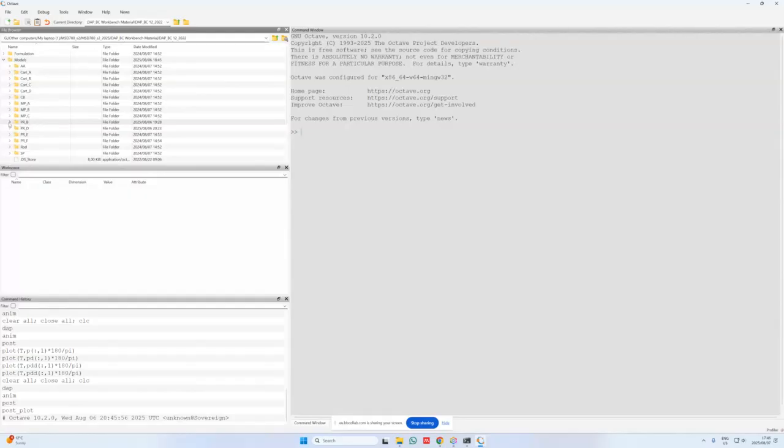For PR_B, you can once again expand it, and then you'll see there are a bunch of .m files over here. These are the files that we are essentially going to change. They are function files. Depending on the number of bodies that we have, the number of points, joints, forces, all those kinds of things, we can update them in these specific input files,